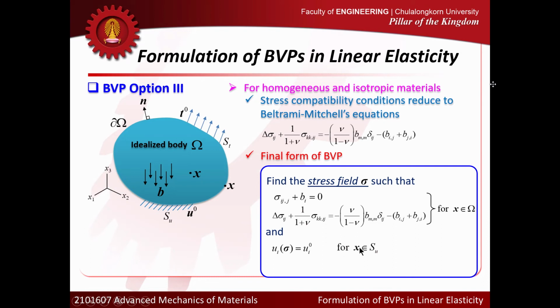To check this boundary condition, you need to confirm that the stress satisfies the Beltrami-Mitchell equation. If that is satisfied, you check that one first. So now you don't need to worry about the existence of the displacement field. You can always integrate the strain displacement relationship to get the displacement field. So this function form exists whenever that equation is satisfied. We need to confirm this condition at every point x on the surface S_U, and on the surface S_T.